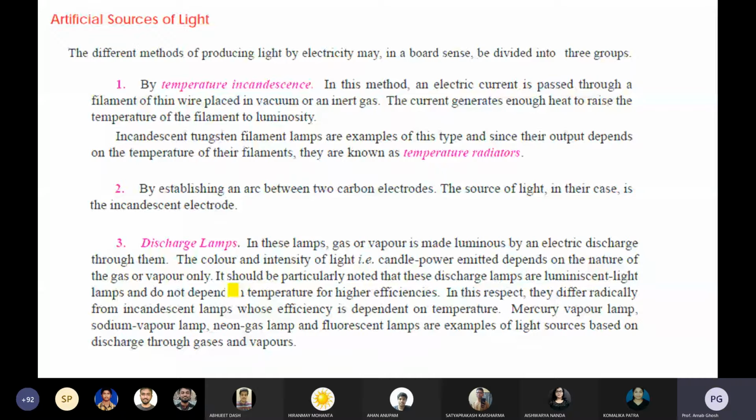frequency circuit. If it is working at high frequency, automatically you will get that amount of inductance, meaning XL, the inductive reactance. We are bothered about the inductive reactance. As the frequency is increased, the inductive reactance also increases without changing the inductor. The inductor value may not be changed, but the inductive reactance can be changed by changing the frequency. High frequency circuits that we use for turning on that CFL are known as the ballast circuit. The rating also gradually decreased.